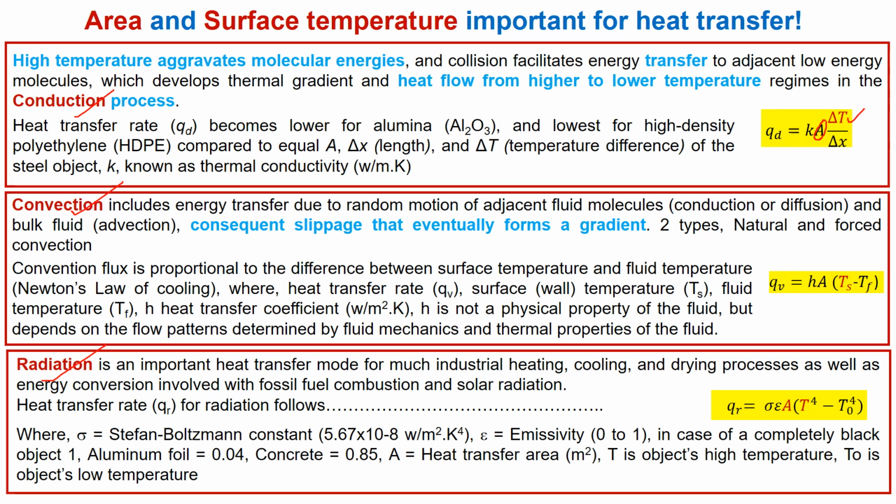Conduction initiates when high temperature aggregates molecular energies, and collision facilitates energy transfer to adjacent low energy molecules that develop thermal gradient and heat flow from higher to lower temperature. Steel has the highest and HDPE polymer has the lowest conductivity, and it follows this equation.